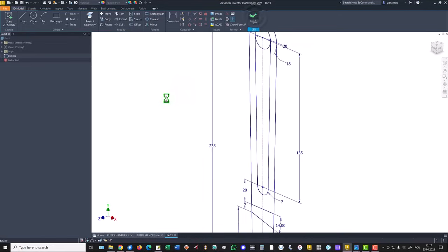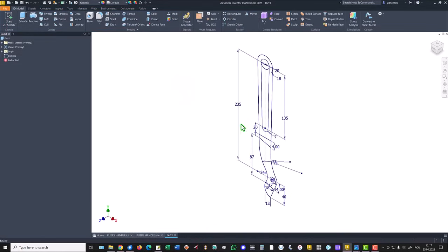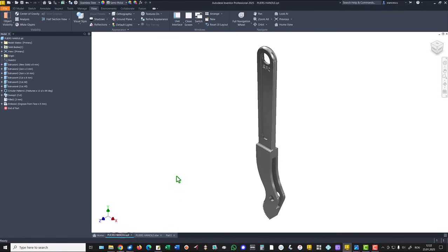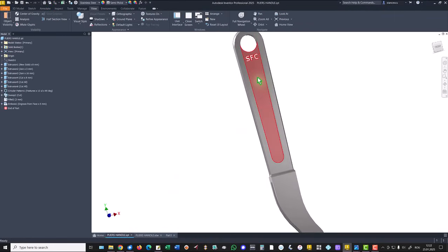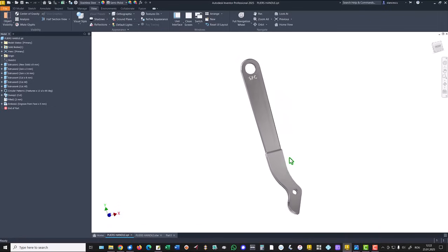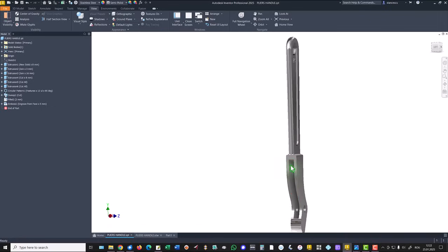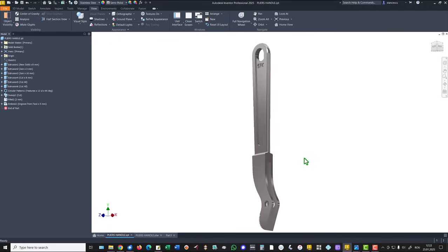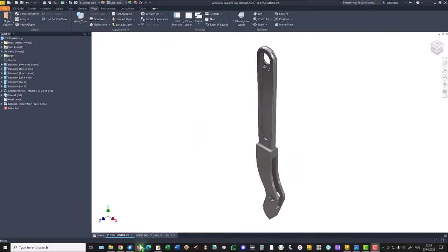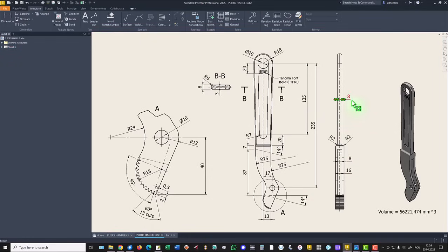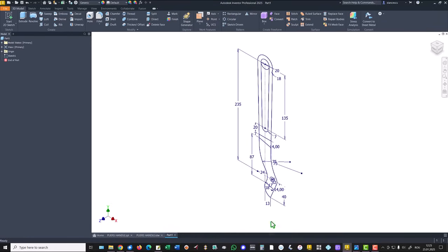Then we have to apply extrusions. There are many extrusions here. This is one, this is the second, this is the third, and the internal void volume is the fourth. Dimensions are here. 8 is this, 3 is here, the thickness, external 16, internal 8. You must be careful because I want to create all these extrusions at once.